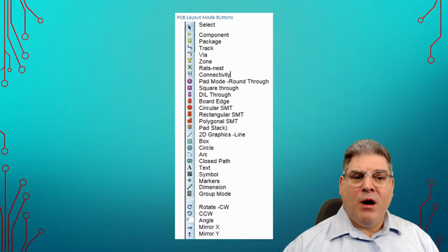So if my resistor R1 happens to be a Res 40, and I pick a package called Res 40, I can actually create a schematic, but the component isn't linked. So R1 is a component that will be connected to, let's say, R2. You have to place those components or it won't actually create your PCB layout properly.